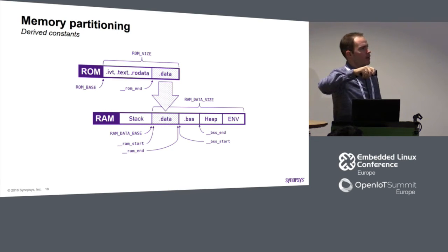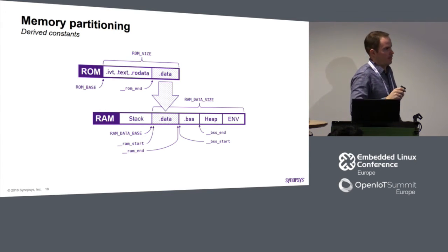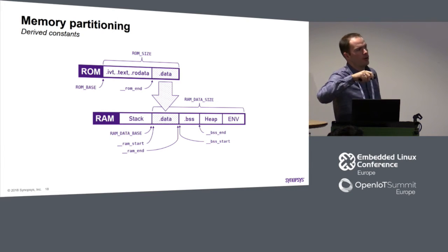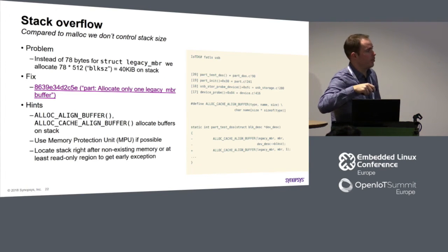would happen. I would silently start to corrupt my data, and somewhere later down the line, like during execution of something else, I would face a significantly worse situation, when I need to debug something which might not even be easily reproducible. So that's why you either put it here and expect an exception to get raised when you access this area, or if you have memory protection units, you may use them as well. It will definitely help.